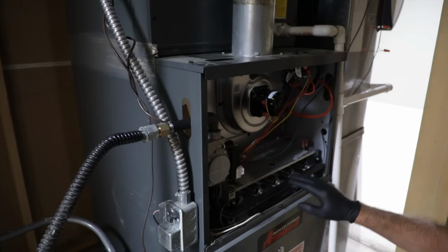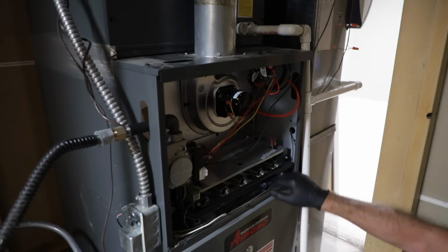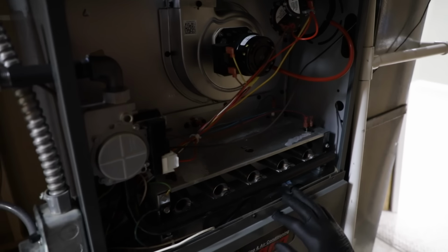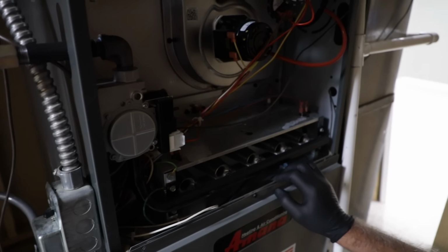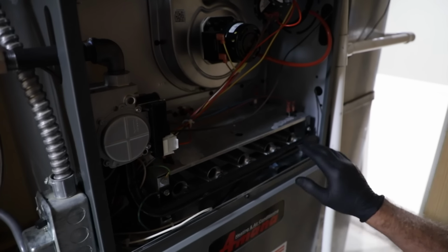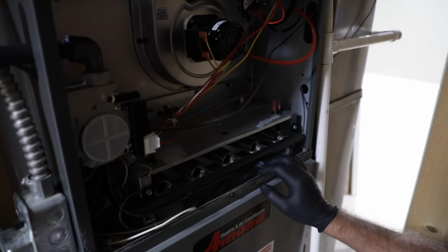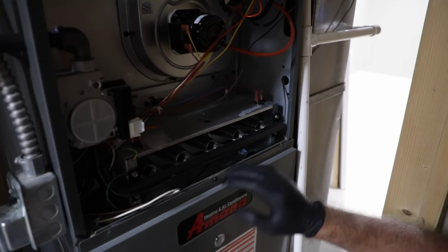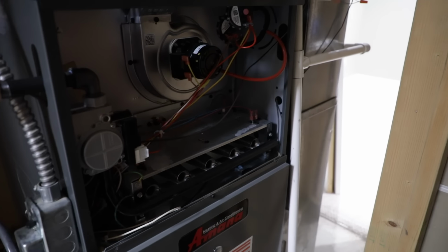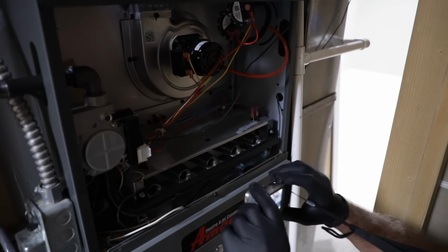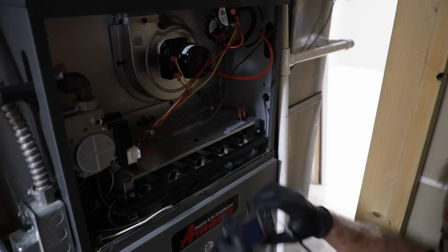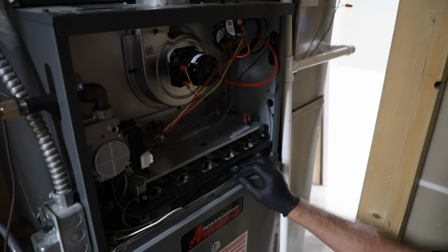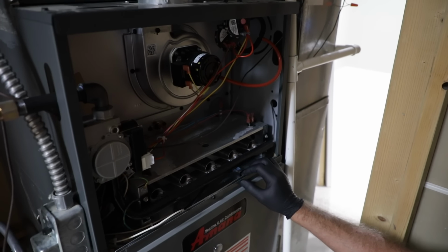I can look at my burners right here. I've got a draft inducing fan, and the first thing I notice now is that after we adjusted the thermostat to ignite the furnace, it is not igniting. The circulation fan has come on, but the burners are not lighting, and it's not attempting to ignite either. So we're going to take a photo, and I'm going to put that in my report. Now probably what I'll do is recommend that they get a review by an HVAC technician, a professional.